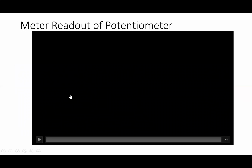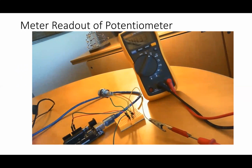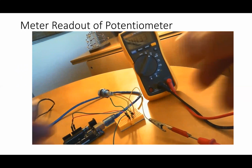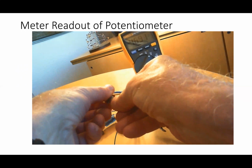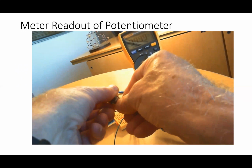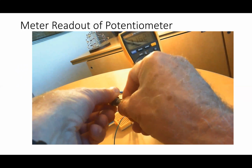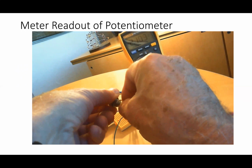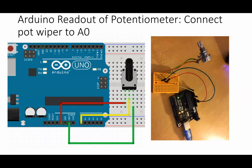All right, we're going to switch our meter over to the volts range and look at what's coming out of the potentiometer. Okay, I see 4.8 volts. And as I turn the wiper of the potentiometer, I see this going down to 0 and then coming up again. Okay, so we have made a nice readout circuit using our digital voltmeter.